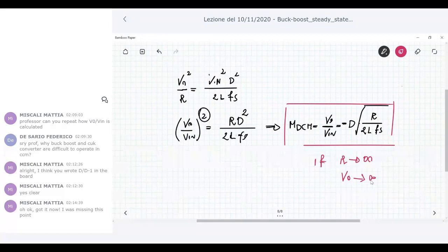Specifically in the lab, when you work on the buck boost or the boost, when you want to measure the output resistance for your measurement planning, and you disconnect the load just to put the load across a multimeter to measure its resistance, typically this leads to malfunction of the buck boost. So please don't do it.